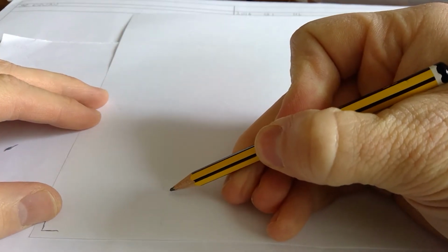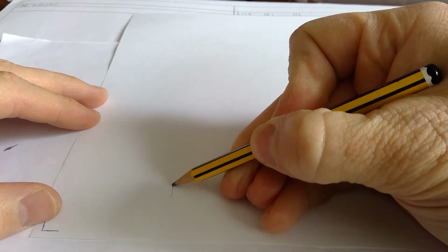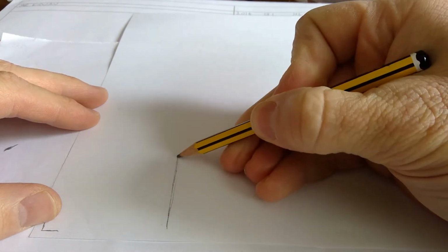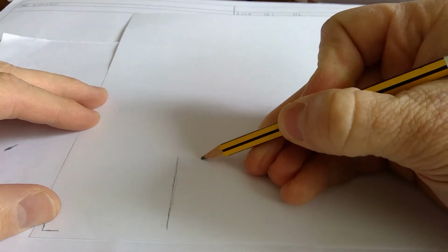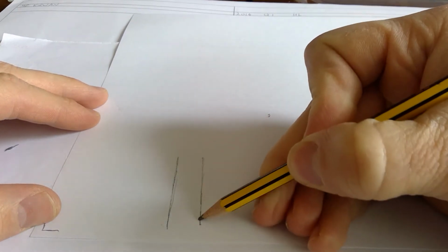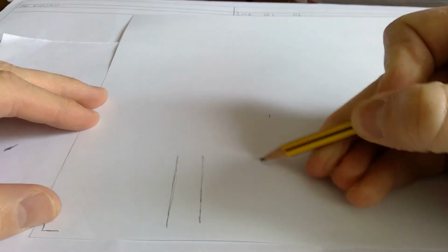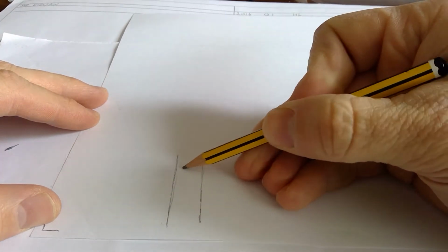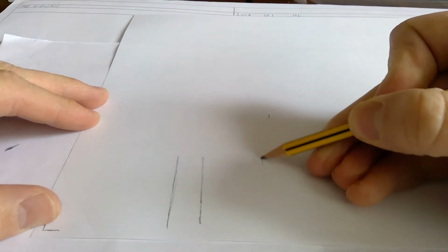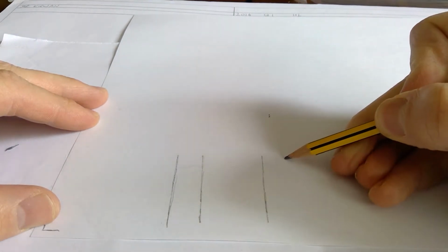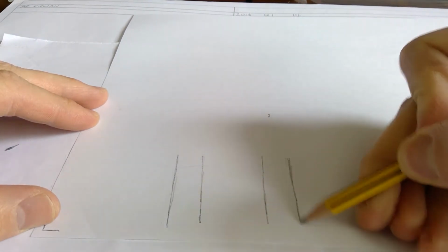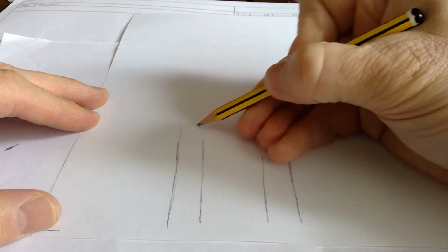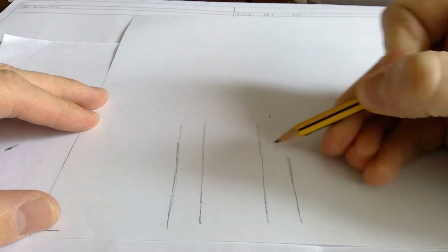So the wall, it said, was a 400mm cavity wall. Lightly first, just to help me mark out my positions. Draw a line for the first side of the wall. 100mm wall. It's quite a wide cavity now. It says 400mm wall, so 100mm will be a block, the external leaf. 100mm will be the internal leaf, and you've got a 200mm cavity. I'm going to just draw that up lightly, up about that height for the moment.